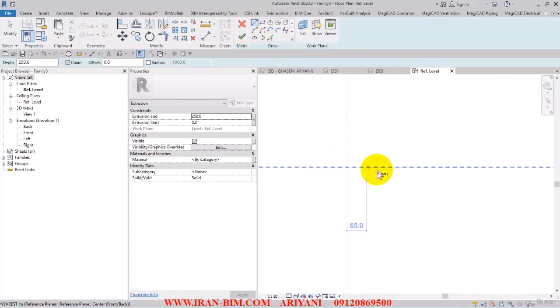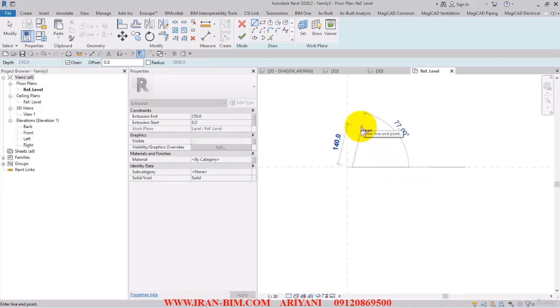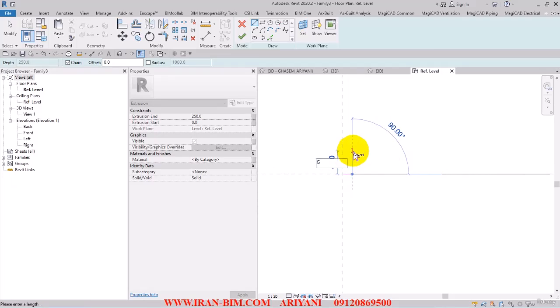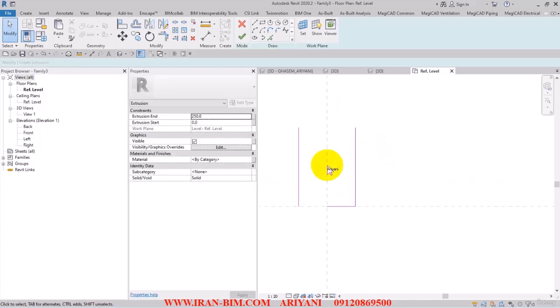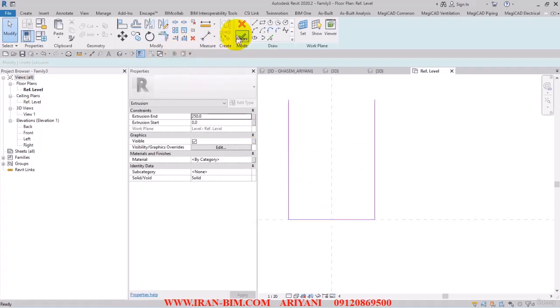So using extrusion, I'll put this here, and I put it equal to 35 divided by 2. And then vertically we have 50, so put this in here as well. Then select this one and mirror it on the other side horizontally. And then using trim, connect these two.